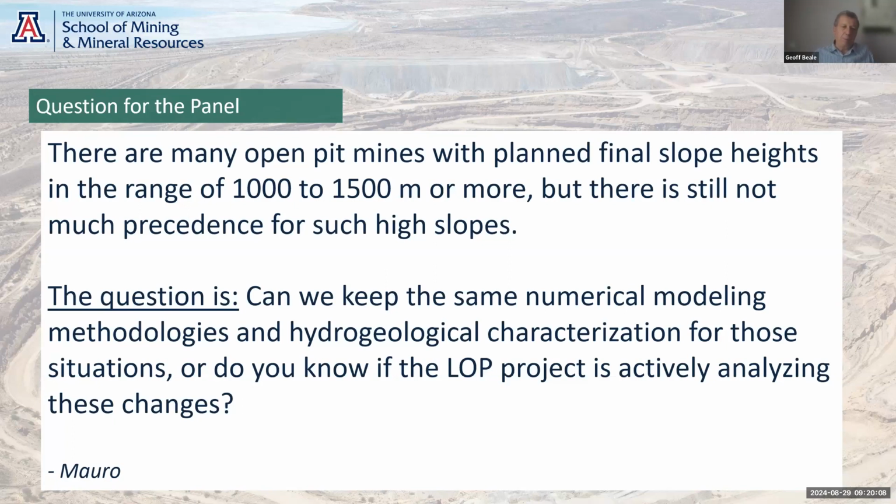If you've got very big pits, if you look at the drainage tunnels that have been put in, they're not all in big pits, but many of them have been in big pits. If you look at, I guess, the 3 biggest pits, Bingham Canyon, Chuquicamata, and Escondida, they've all had drainage tunnels put into them. So I think that's mainly the difference, is that when you go for these big walls, it may make the idea of a drainage tunnel more attractive.